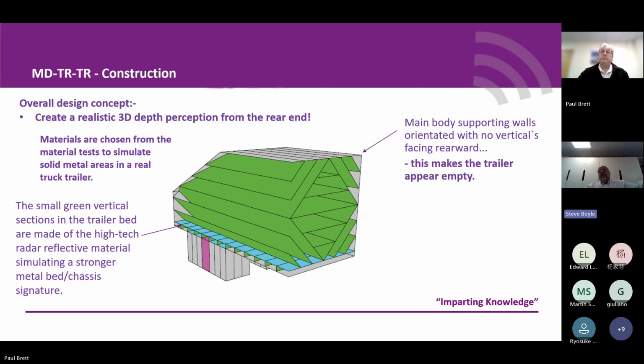The more sewing and the more complex amount of sewing and development into this, the more walls you have, the more sewing you have, the more cost you have. And this is the reason why it's not what we call an airtight target. An airtight target is where you pump it up, seal the valve, and leave it. To make those seams something this big and airtight is a lot of money and a lot of complexity, to hot weld and seam all the seams so there's no air coming out of it.